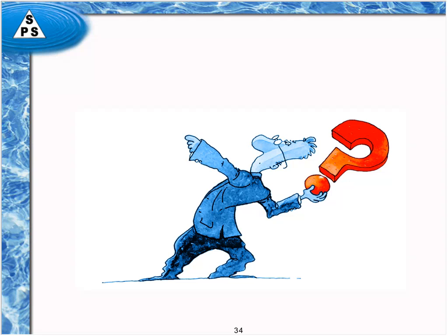If it was daily, you would actually prevent any chance of biofilm development. Remember, hot water sanitization does not clean the dead biofilm away; it just kills it. And so if you leave all this dead debris behind, it winds up being food for further, or more rapid, development of biofilm.